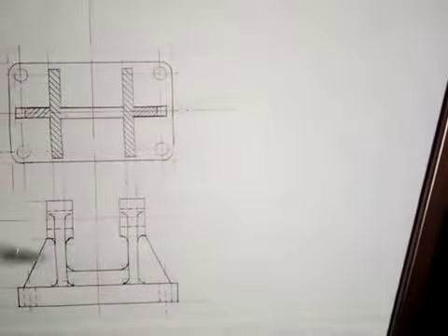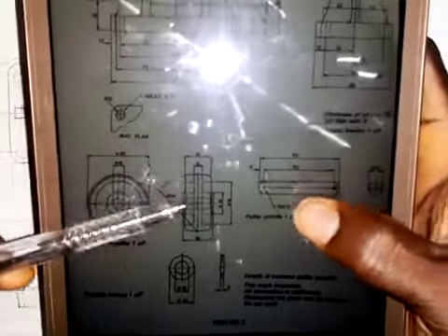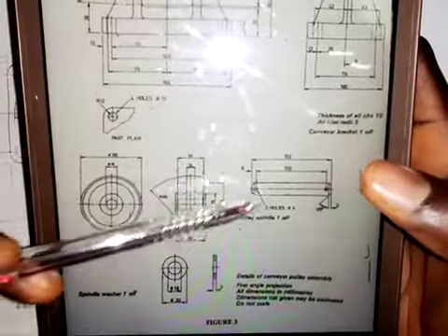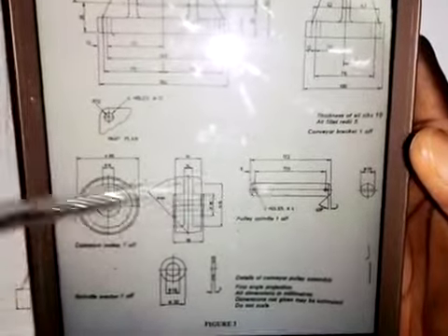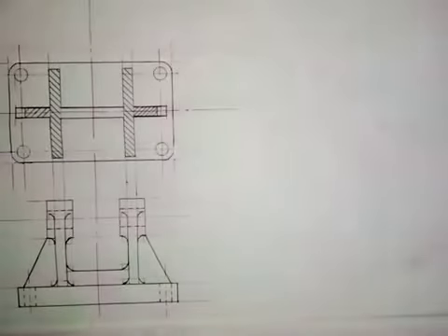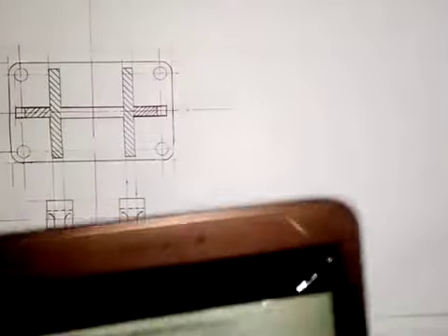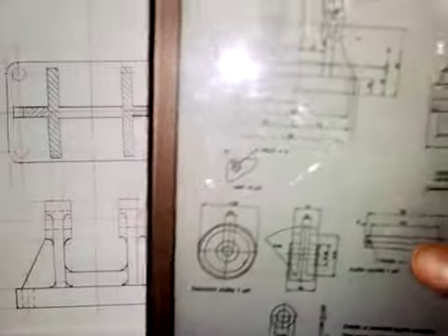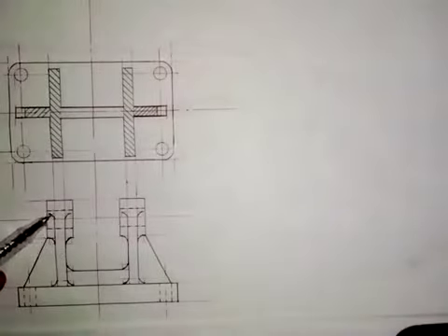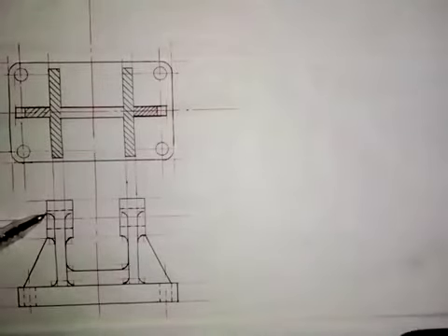We are going to redraw this, and we are going to put in some things. We are going to put in this pulley and also this spindle and the washer. We are going to put them there. So that's what I'm going to do. To draw the sectional view, some parts will not be there. We are not going to see this part there, and we are going to see the inner part of this object. And just look at the way I'm going to do it.